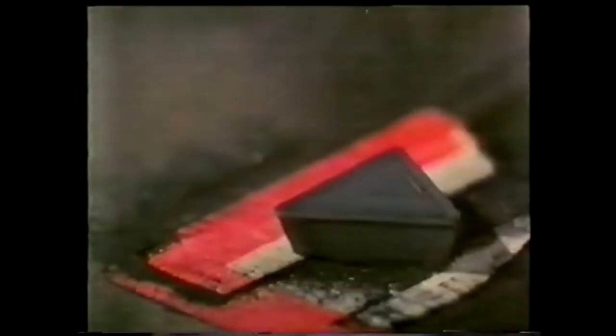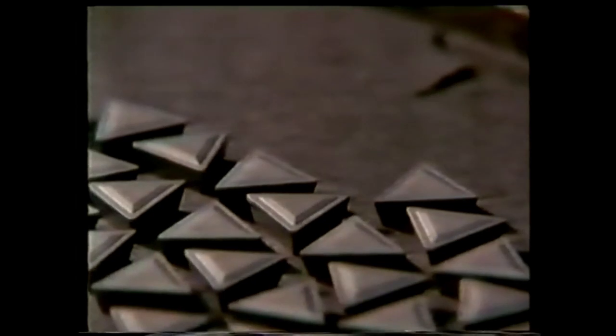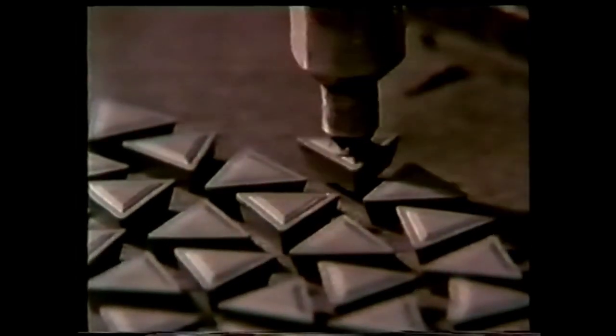Cemented carbides normally contain 70 to 90% hard particles, together with 10 to 30% cobalt binding metal. The more cobalt present, the tougher the cemented carbide. Unfortunately, increased toughness results in decreased hardness and resistance to abrasion. So the next stage is sintering in an oven at a temperature in the region of 1600 degrees centigrade. A cover gas of hydrogen prevents the oxygen in the air from damaging the insert. The result is a fully hardened insert.